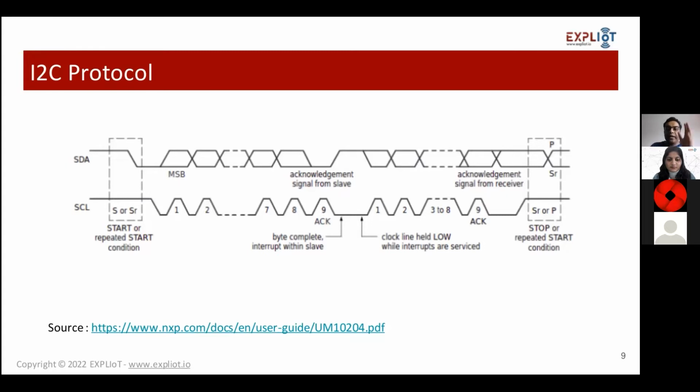Now, let us say it wants to save that data into memory. It will pause that communication, stop at the moment, and store the data over a different I2C channel, or possibly the same I2C channel. It uses the address of the memory, which has a 7-bit address, initiates communication with the EEPROM, gets a positive acknowledgement, and then stores the data into that memory bank, right? So that way we can have I2C-based communication. For everything, always remember the ACK is the most important bit in that scenario.